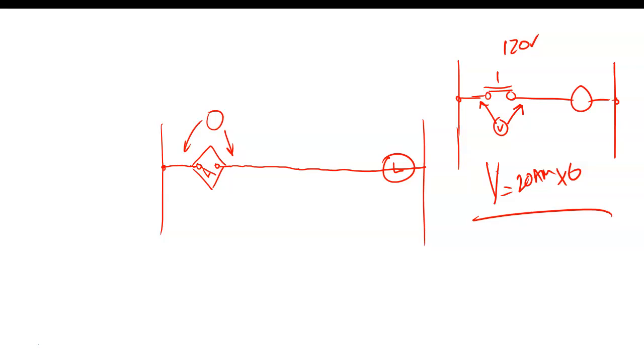How much does the fuse drop? Well, it drops, right? How much does a good fuse drop? Pretty close to 0. A fuse will have to drop a voltage because it takes a voltage to blow it, right? Understand? The lower the current rating, the more resistance it has. I've seen a 1 milliamp fuse maybe have 100 ohm resistance, but that's at 1 milliamp, 1 millivolt, right? So if we measure across, it still is going to drop 1 millivolt, right? You understand that? So fuses drop a little bit of voltage.